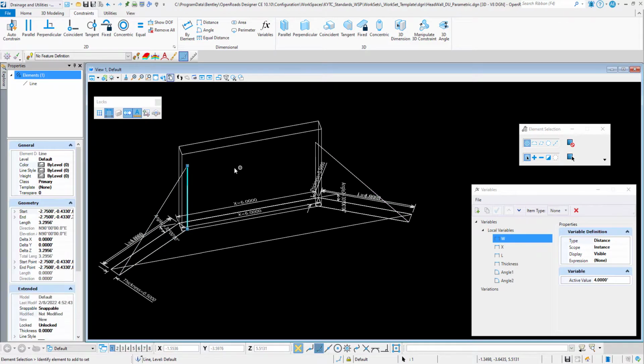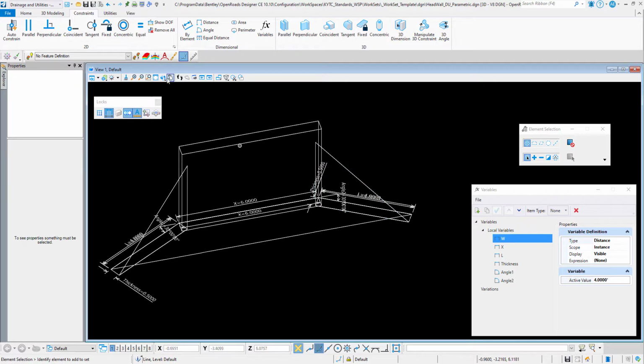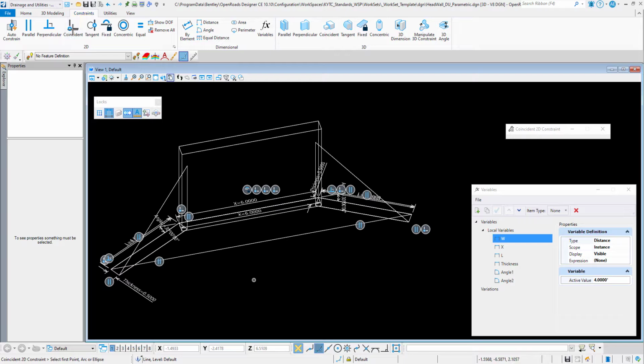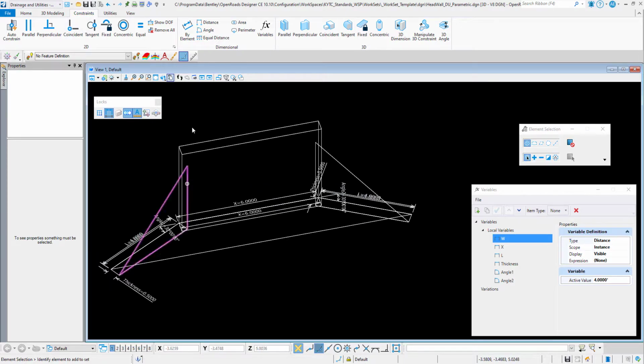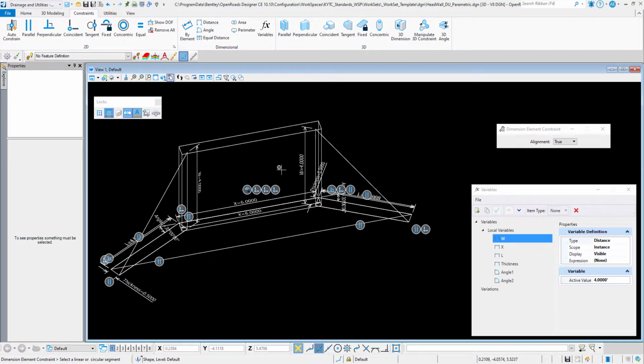And then once I did that, I drew what I wanted. I don't need those helper lines anymore in this particular case, so I deleted them out. Now I want to make sure that these kind of move inward and outward. So I have my bottom shape that is constrained appropriately, but these wings, the triangles, are not constrained anywhere. So I'm going to make sure that I constrain them to the height, and I'm going to constrain the lengths.